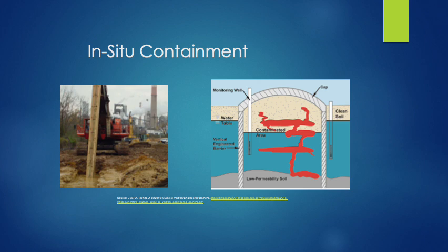Often a low permeable inclusion, either soil or bedrock, may provide bottom containment of the impacted mass, but in some instances it may be appropriate to use horizontal drilling techniques to provide such protection. Lateral structures may also be installed. Vertical slurry walls or vertical sheet pile walls may be installed. This prevents the mass from migrating outward.